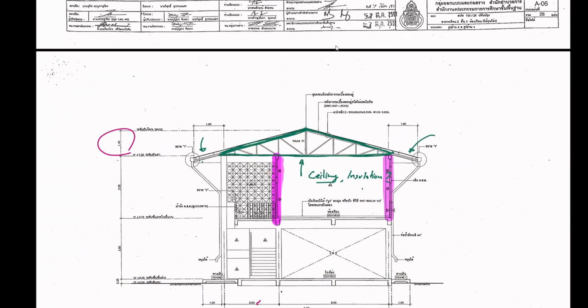And one more thing, I'm going to summarize here. Because we use one member to create the top chord and bottom chord, you only need to obtain the maximum force anywhere on the member. You don't have to design for everything. You just find the maximum force and design the top chord and the bottom chord, and then all the diagonal and vertical members.